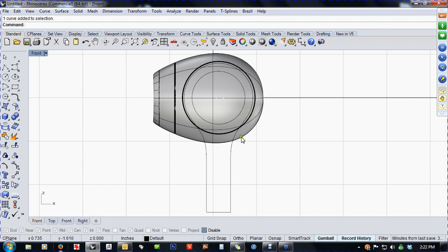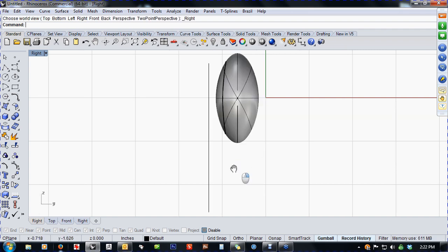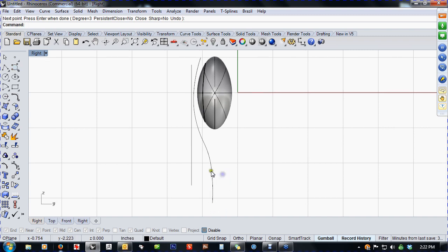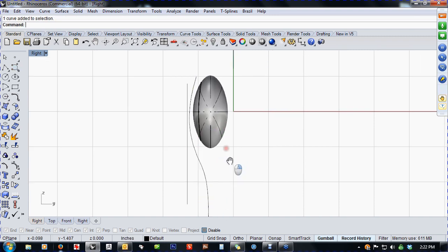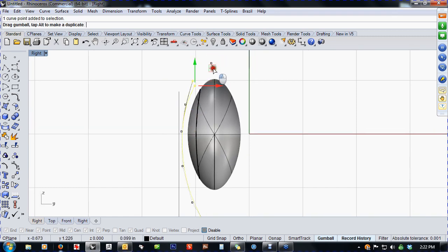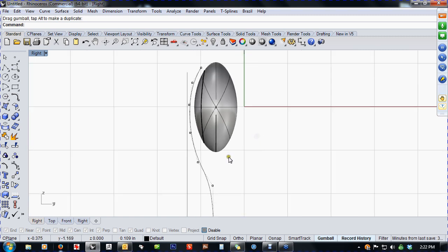So how do we make this shape? Well, I'm actually going to do it from this view. The way that I'm going to do that is I'm going to use a curve to kind of lay down a shape of how I want that thing to kind of transition. And I'm going to turn the points on for this, using points on. I'm going to adjust a little bit because I didn't quite nail that curve the way that I wanted it to look. So let's peel that in a little bit. I like how that's a little closer and then it peels out.